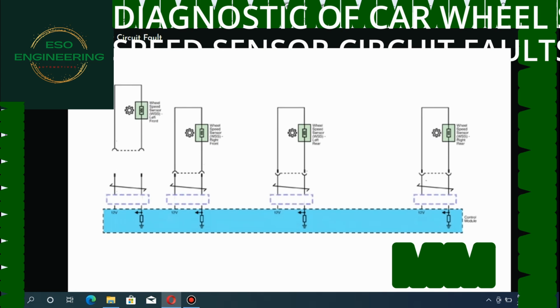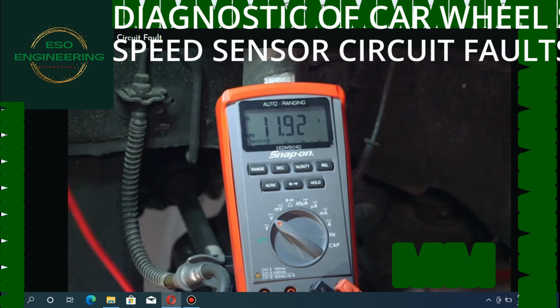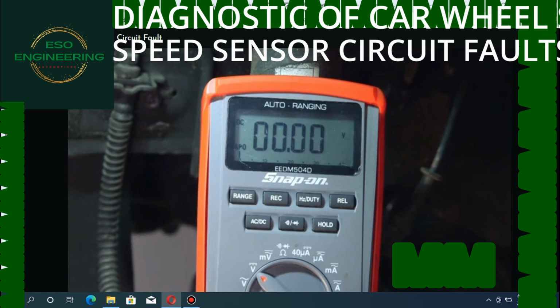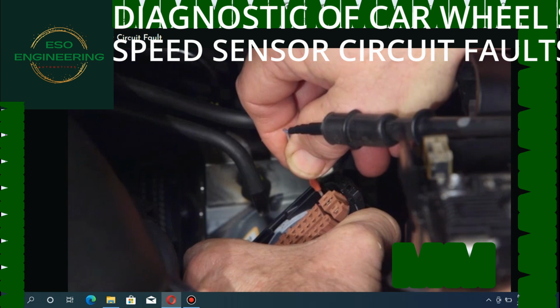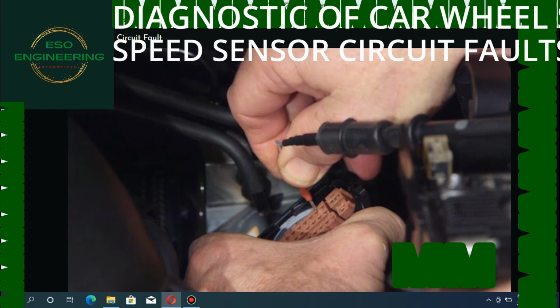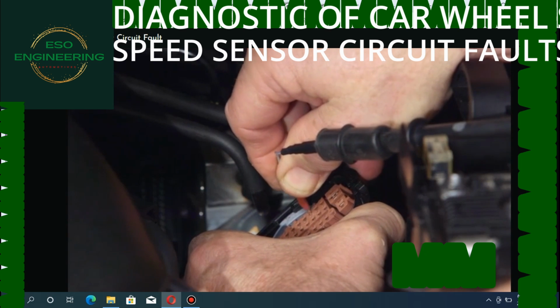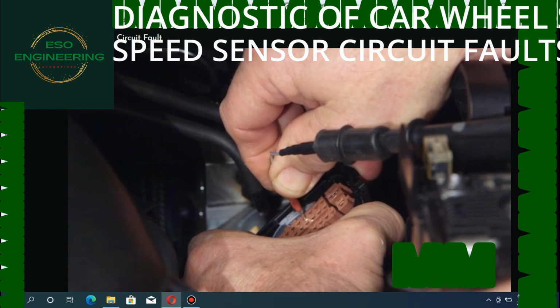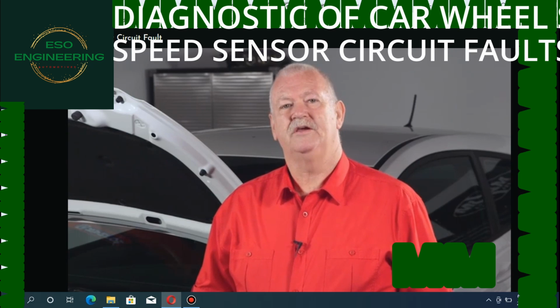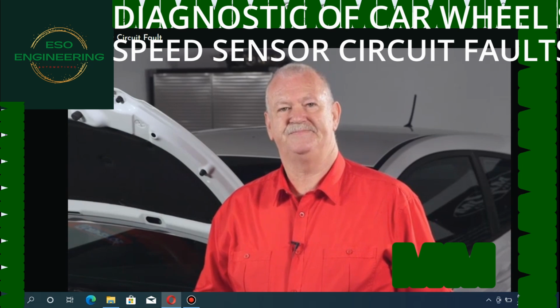Disconnect the module and retest. If the voltage is still there, then the short to ground will be in the wiring harness. If the voltage is now gone, then the fault will be in either the module or a ground from the module shorted to the signal wire. To test for a shorted signal wire, connect one probe of the multimeter to the sensor connector 12-volt reference terminal and see if there is a connection to any other terminal in the module connector. If there is no short to ground, you'll need to check for an open circuit.